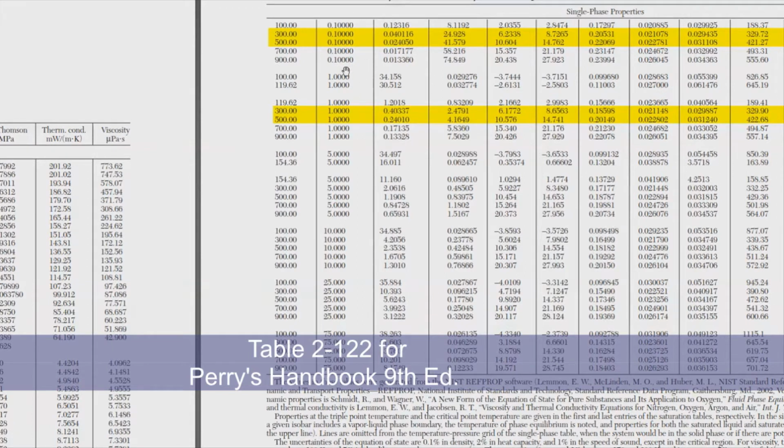If the problem says that there's 2 atmospheres, if we convert that to megapascals, what you will be getting is 0.101325 times 2, so that's around 0.20. Now in that case, since we don't have any value for our 0.20 megapascal, what we need is to interpolate in between this 0.1 and 1. Now the idea here is to do some kind of double interpolation.